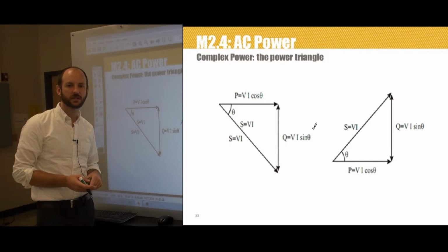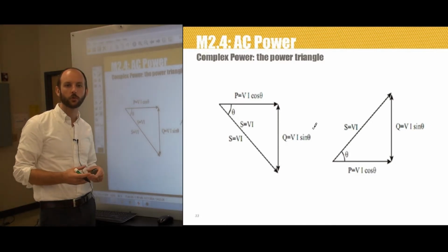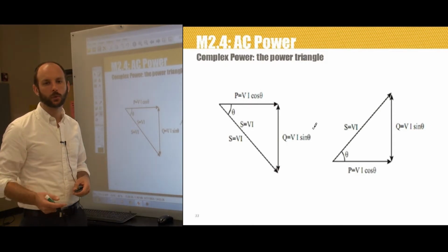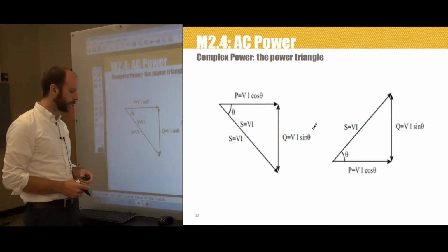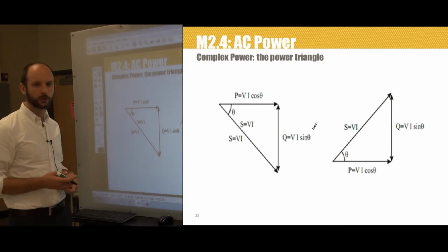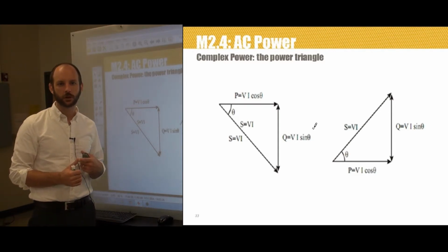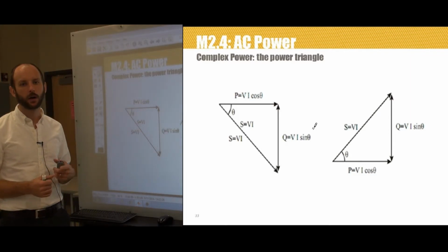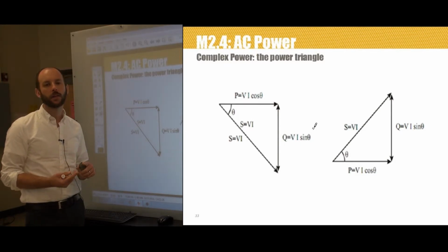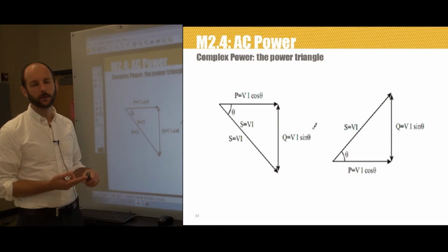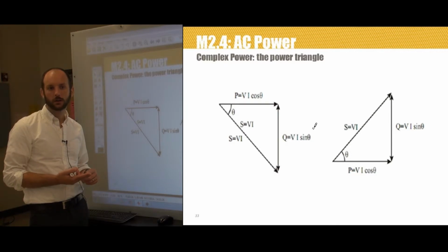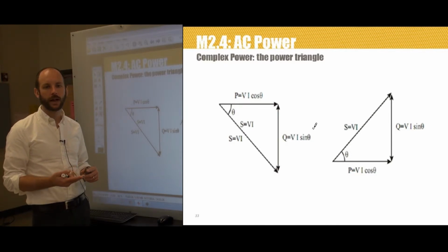When we consider the entire system, the different power factors of individual loads will combine together into one aggregate power factor for the set of loads, and that's kind of an advanced topic that we will talk about later. So if we were interested in what are some of the sources of reactive power, what things in the system produce reactive power? Well, primarily it comes from generators. Generators can supply reactive power. Capacitors, interestingly, are thought of as supplies of reactive power, and then lightly loaded transmission lines supply reactive power. So if I have transmission lines that aren't carrying a lot of current in them, they actually will supply reactive power.